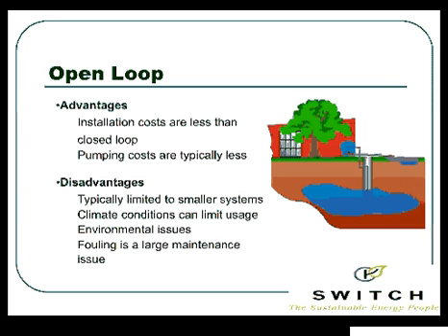And again, like I say, fouling becomes a bigger factor. And by fouling, what that means is now we're taking that dirt and it's getting into our system because it's open. And we now get fouling on that heat exchanger. So that heat exchanger gets dirty. And that means we lower our system efficiency because we have a dirty heat exchange surface. Okay.